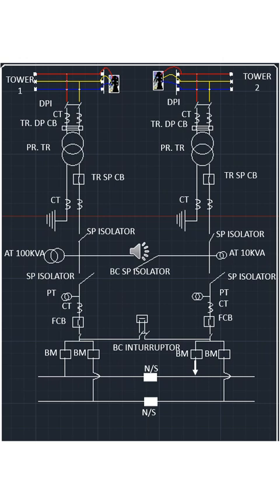So to solve this, we are raising the voltage. Nowadays we have raised the voltage from 66 kV to near about 735 kV. That means 7,35,000 volts. But it is somewhat rare now. Usually we are using 132 kV or 220 kV and somewhere 400 kV. These three voltages, 132 kV, 220 kV or 400 kV, are somewhat popular